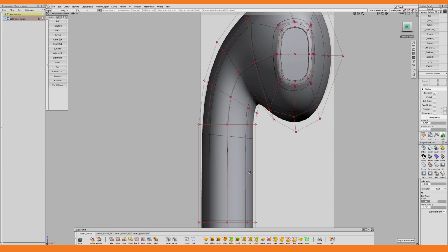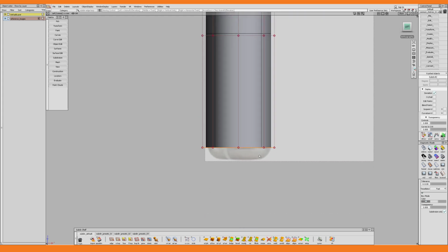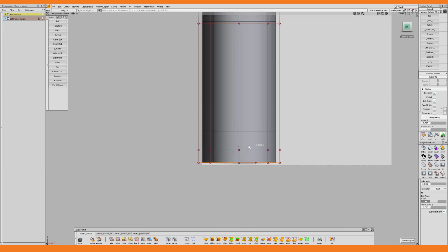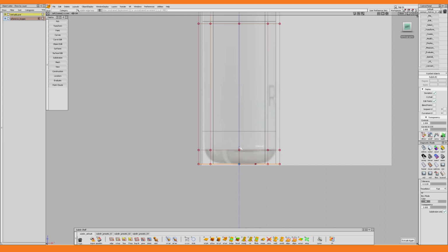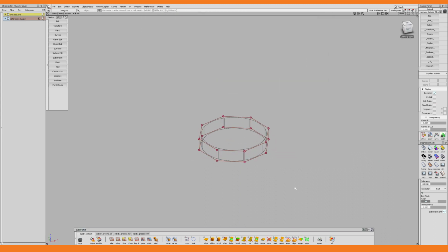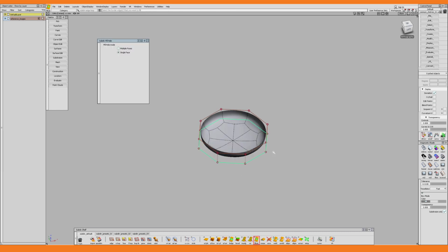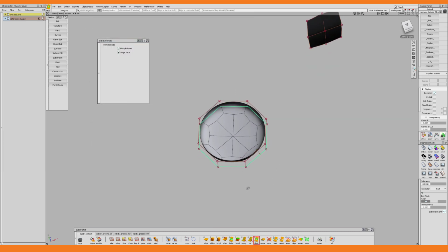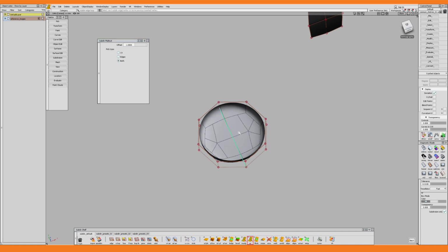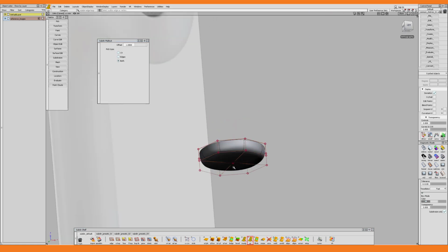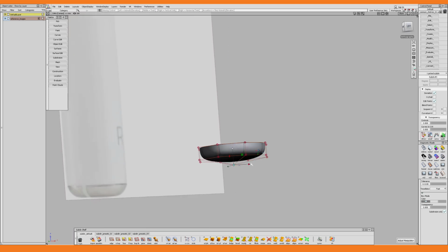And creating this piece will be fairly straightforward. First I extrude the bottom edges to create some new faces. And then I use extract on these faces to turn them into a separate object. Just like before, I need to fill the hole in the bottom and then sort out the topology by way of the cut tool. And then it's just a matter of transforming vertices until our model is matching with the one in the reference image. And why not start with this one?